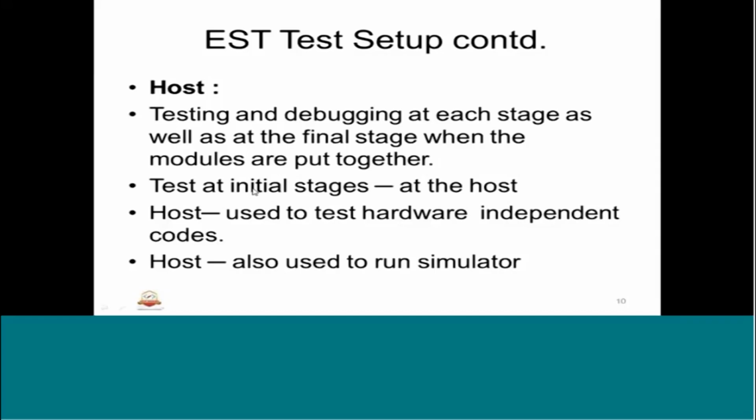So testing can be done at initial stages at the host side. That means having developed some piece of software, we can use the same host for testing it, like whether it is working as expected or not. And in the host itself, we don't need to program that onto the target. As I said, there is independent software code that can be used in the host itself, wherein modules like algorithms and those things can be run and tested on the host or the PC.